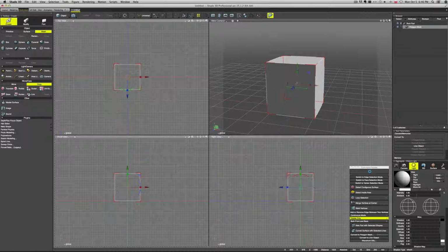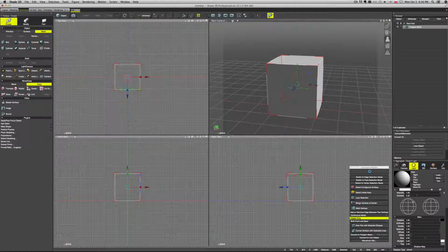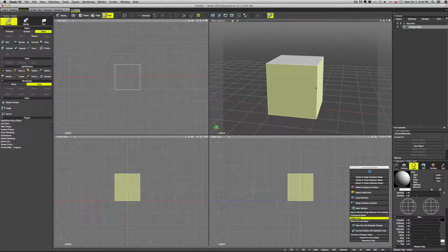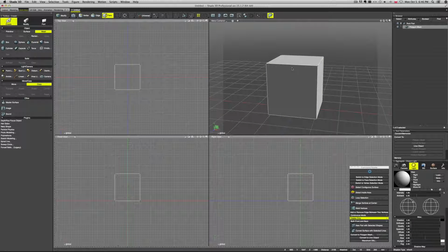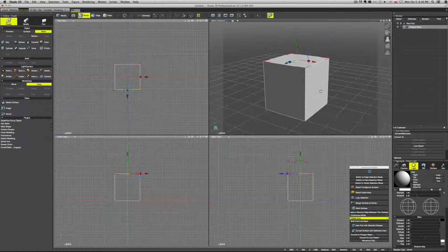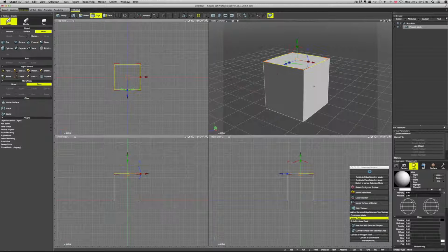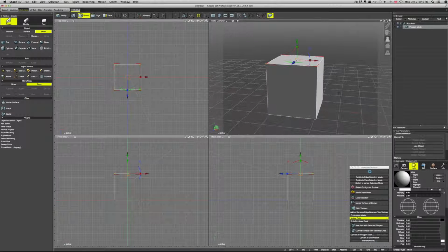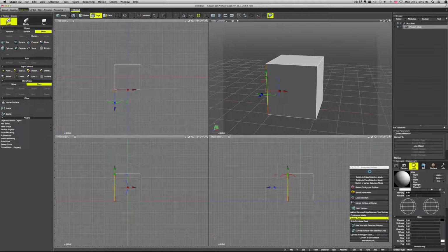We basically switch between object mode, which is the mode where we have the entire thing, and modify mode, in which we select faces, edges, and vertices. Right? So object and modify mode, it's good to have them assigned to different hotkeys, so you can quickly switch between one and the other. Or you can use these top icons.